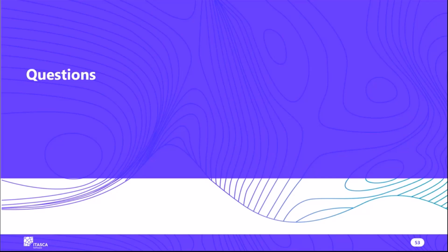Question: how can I perform strain burst and shakedown rock burst event modeling? I don't know. That's a big question. I mean, if I was doing strain burst, I would use dynamics. Well, maybe. It depends what you're trying to get out of it. You would have some sort of stressed system, a bunch of blocks with a bunch of joints that are under high stress, and then you would have to perturb it somehow to see that thing burst. So, maybe weaken the joints slightly or apply a small load or excavation or something to see if that thing